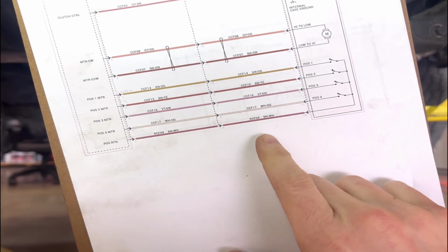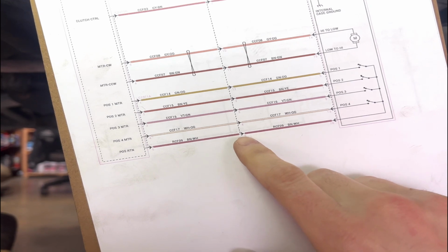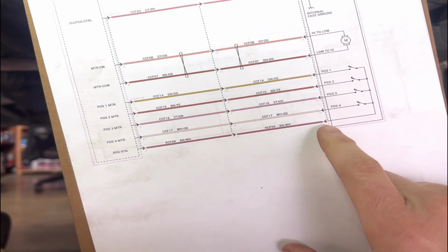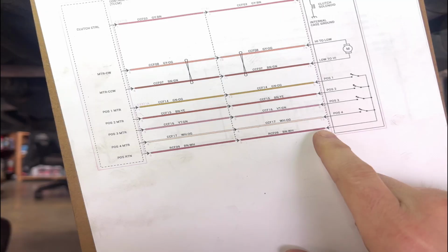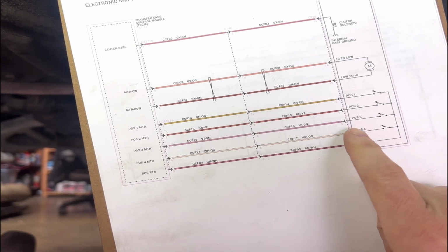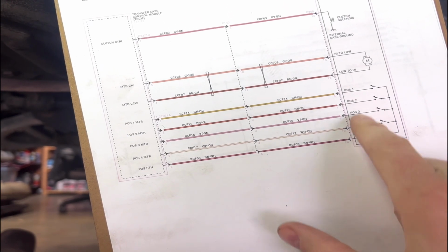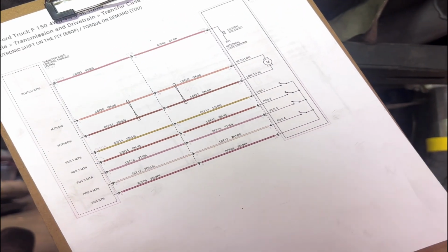Now, what I'm going to try to do, because the car's still in the rack and I can't get to that transfer case control module very easily because the door doesn't open, I'm just going to leave this test light plugged in here. We're going to go and actuate the 4-wheel drive and see if any of those codes go away and then which one of these changes. So let me set this up.